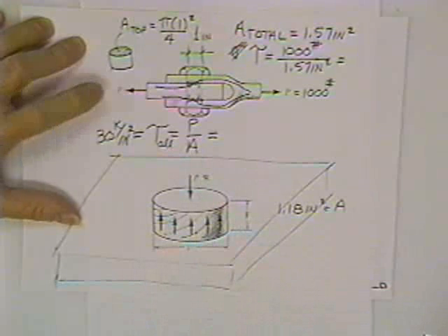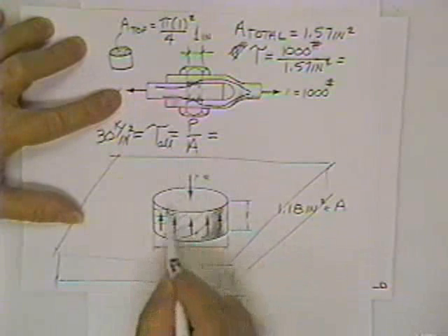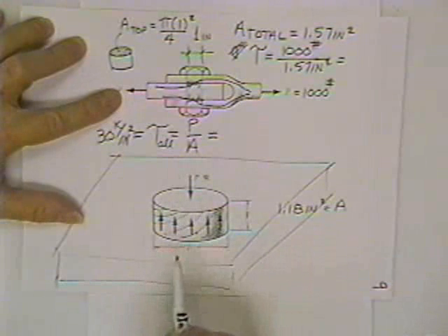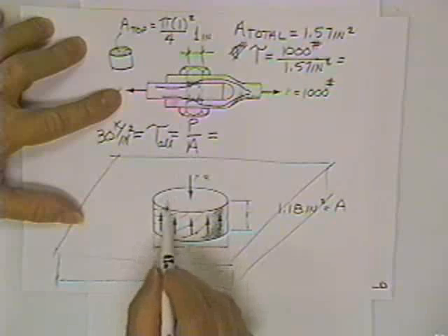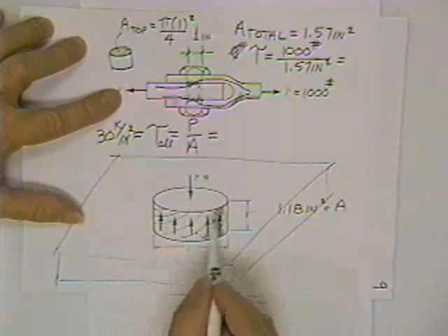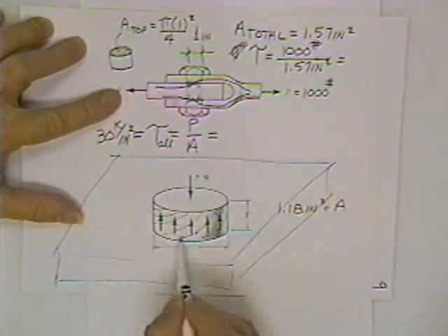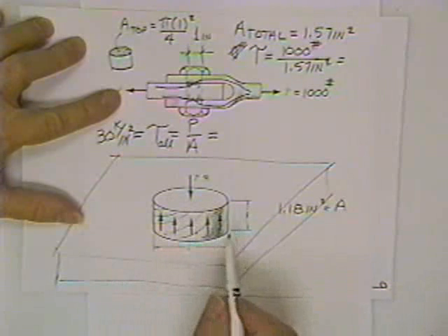Again, you find the area the same way as you did up here. If you take a punch, poke this thing out, let it drop on the floor, and pick it up, it'll look a little bit like a dime. The top's probably all rusty, the bottom's probably all rusty, but I guarantee you this surface around this tin can part is going to be nice and shiny because it used to be holding up the load, and now it has failed.